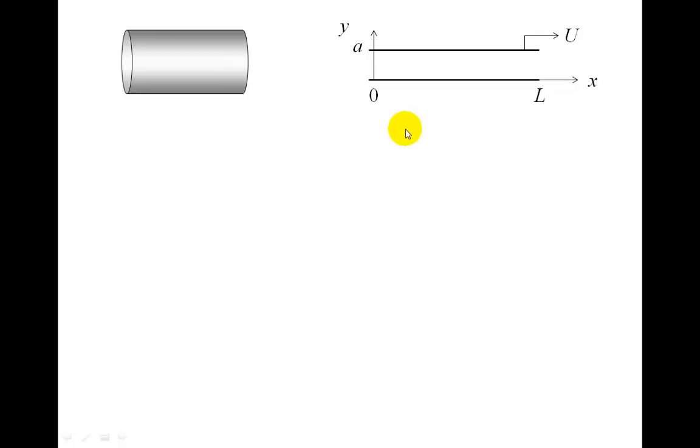Let's first consider now the forces applied to this tube. We have pressure on either end of the tube, so I'll call that P0 for the zero end, and that's pushing the mass forward, and then we have PL, the pressure on the other side, pushing it backwards. And in addition to that, because there's flow in this gap, we have shear stress, tau Rx, applied to the tube. We think since this is moving forward, that shear stress should be pulling backwards, although what really happens also depends on the pressure difference, P0 minus PL.